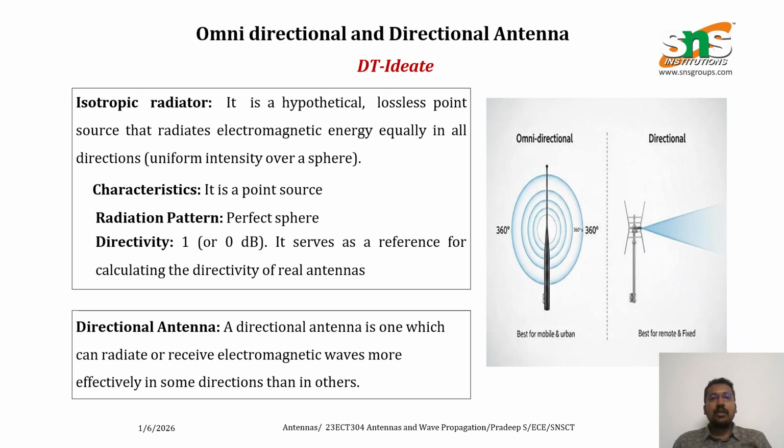Current on a thin wire is created by the movement of free electrons. In a lossless two-wire line, reflected traveling waves combine with the incident wave to form a standing wave pattern. If the spacing between the two wires is very small, the fields from each wire cancel and there is no net radiation. Radiation occurs individually from each wire due to the time-varying nature of the current and the termination of the wire.